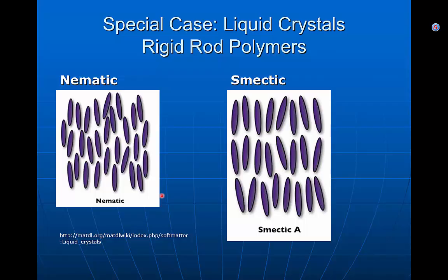Okay, there are a few liquid crystal polymers that are commercially significant. They're interesting because while in the melt, they organize into crystals, and as you cool them down, van der Waals bonds form, and they become solid. And you get very, very anisotropic properties. You have fantastic properties in the direction of the rods, and not such good properties perpendicular. The material you're probably familiar with that's a liquid crystal is Kevlar, aramid fibers that are used for ballistic protection and protective clothing and all kinds of things.